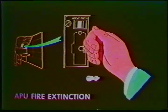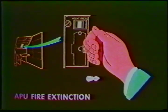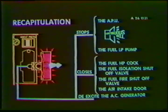In the cockpit, pulling the fire handle causes the APU to automatically shut down. In addition to this, the continuous bell is canceled, the fuel valves are closed, and the AC generator is tripped.